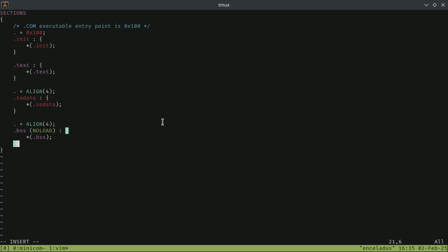With the way we've written this linker script so far, we need to make sure that we place the BSS declaration at the end of the script so we don't end up misaligning the load and run addresses of the other sections, but we can address this limitation in the future. We can also define symbols inside the linker script that'll help our program identify where things are. Let's mark the start and end location of the BSS section along with its size so we can have the runtime zero out the memory before doing anything.